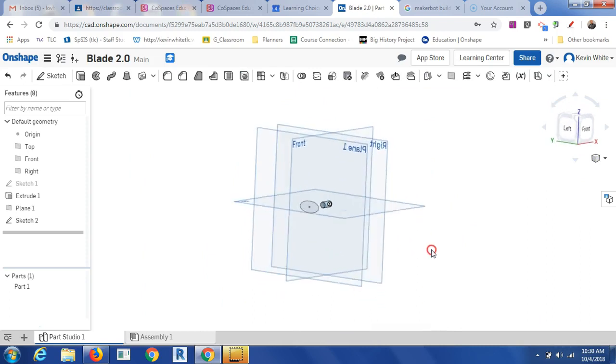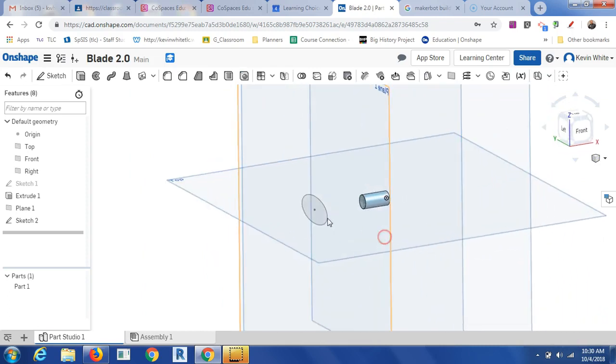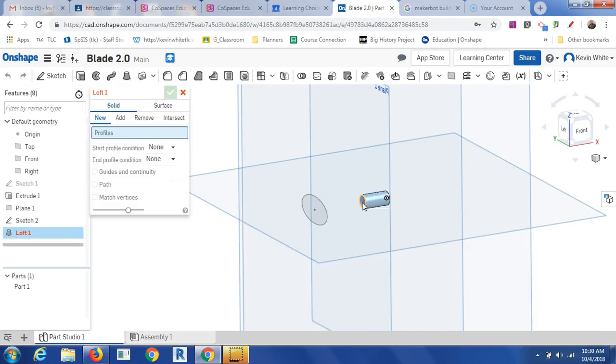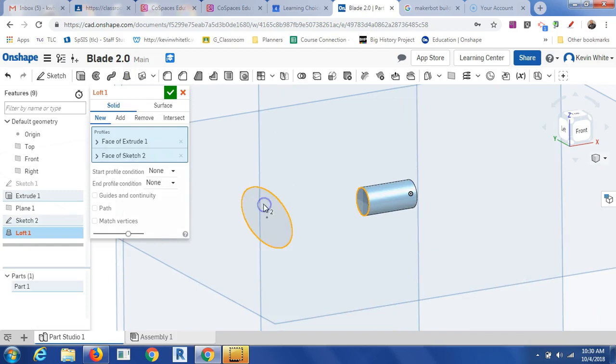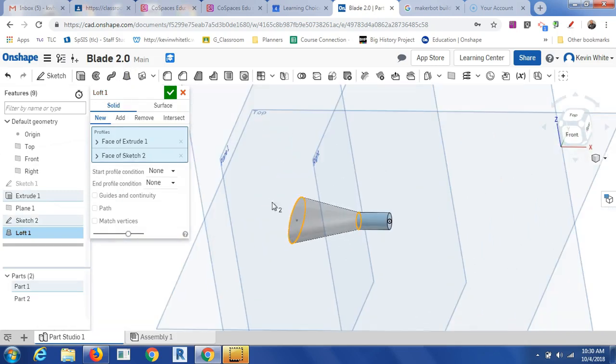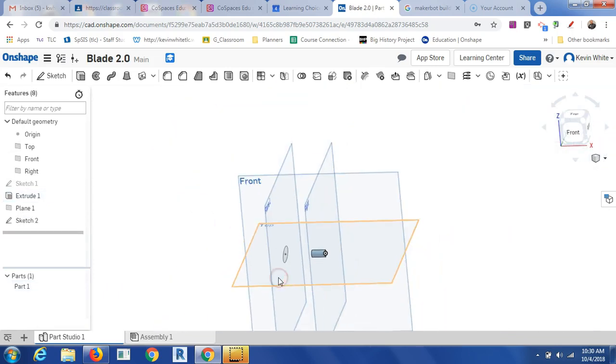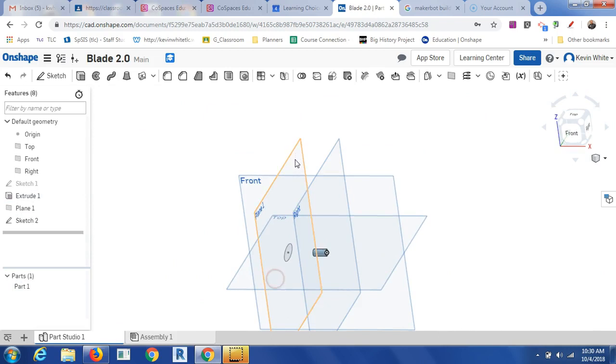And what's nice is you can actually take the end of this shape and loft it into this as well. So I'll really quickly kind of show you how that works. We're going to take this point right here and loft it into this, and now we have this kind of tapered extrusion that pops out. So I'm going to undo this loft, because what we're going to do is one continuous loft that connects all of our planes. And then we're going to offset from here.